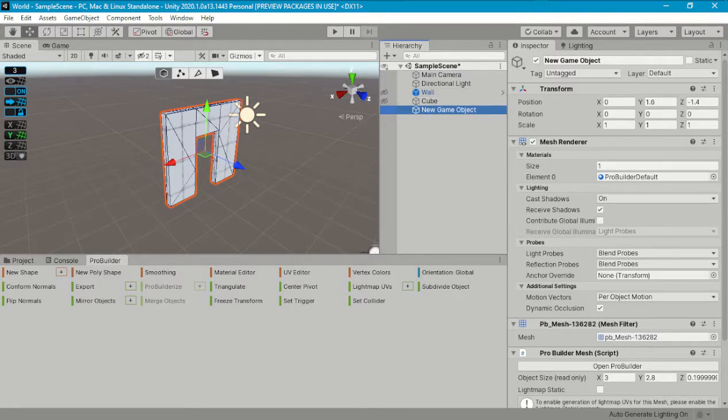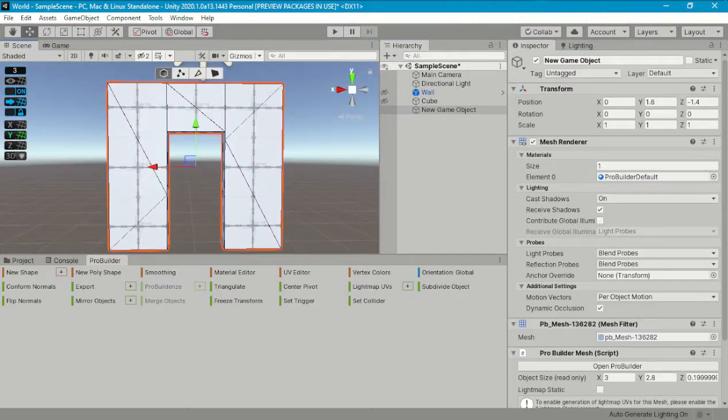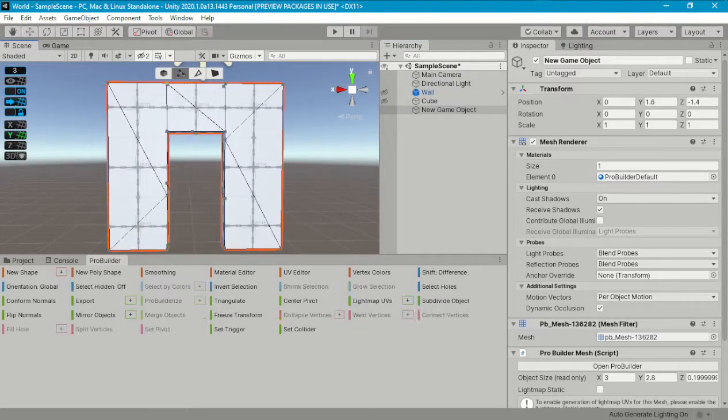If you remember from the previous 2 episodes, it should be obvious that the triangle count is not optimal. We can get rid of at least 4 triangles. 8 if the hidden faces are subdivided in the same way as the visible faces are. Let's optimize this mesh. Select vertex mode. On the left side, click on the bottom of the door, then on the middle vertex while holding Ctrl.